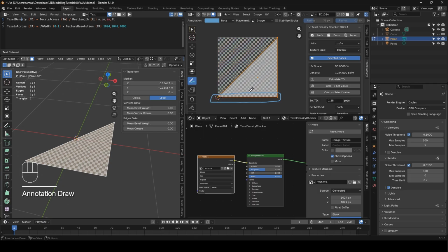So it's not 0.5, it's still one of the UV grid, and then we've also still got the full 1024 pixels. Basically that's because even though the face is cut in half, it's still being mapped at 1024 pixels per meter on the object that it's attached to. So even though we use half the number of total pixels, the size is still the same.